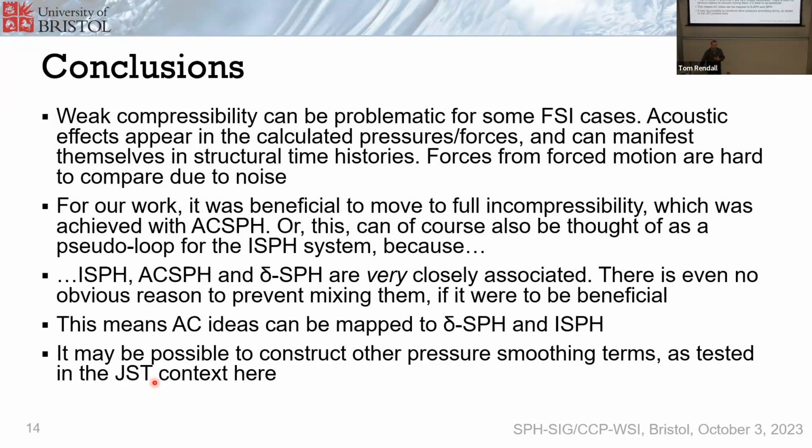So, I use artificial compressibility for other things. And if it's part of the physical model that you do have acoustic waves and you do want to capture them in some form, then that's a better way of approximating them, instead of having a fully compressible set of Navier-Stokes equations. So using artificial compressibility, you capture the acoustic properties, the ones that should be there do remain in the system, while all the noise does get removed.